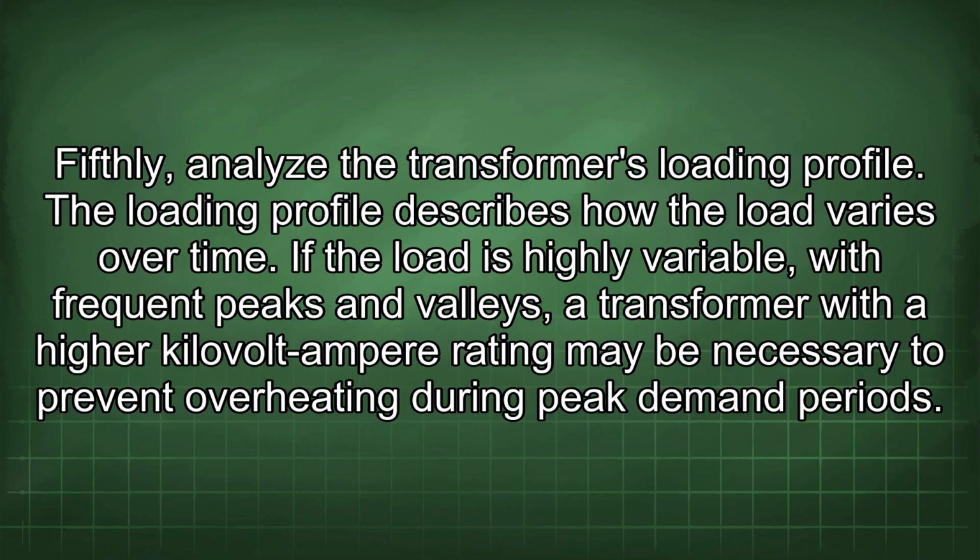Fifthly, analyze the transformer's loading profile. The loading profile describes how the load varies over time. If the load is highly variable, with frequent peaks and valleys, a transformer with a high kilovolt ampere rating may be necessary to prevent overheating during peak demand periods.